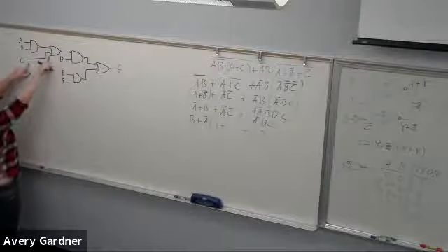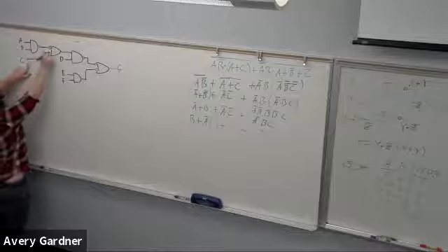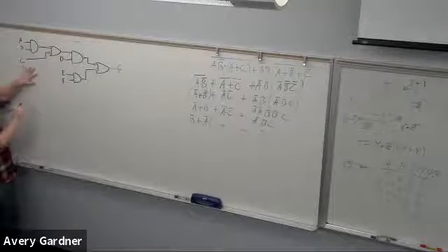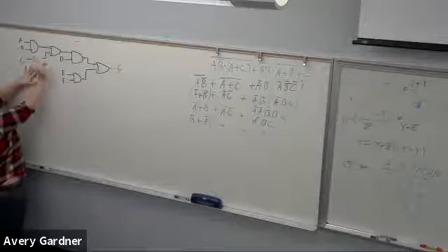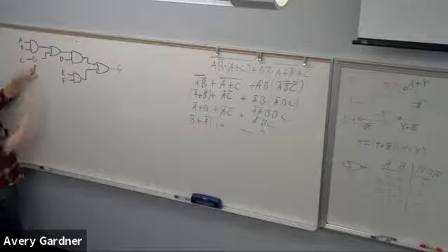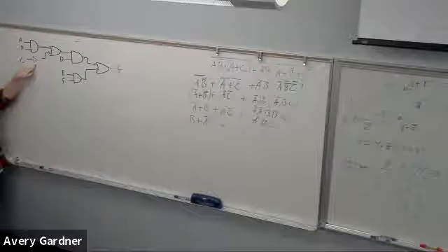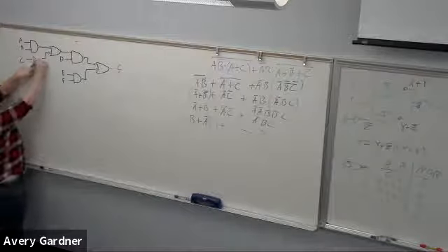So now this has a second bubble that needs to get pushed, but there's no gate to hit. So here I make the gate, and then I push that bubble into the buffer, right? Remembering a buffer, the output equals the input, and if I stick a bubble on the end of it, it's an inverter.